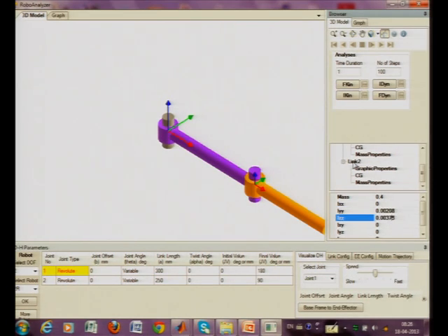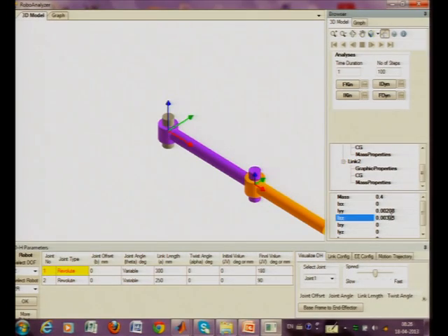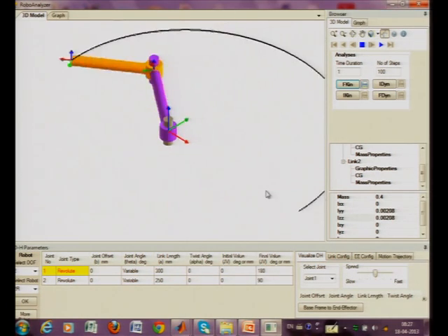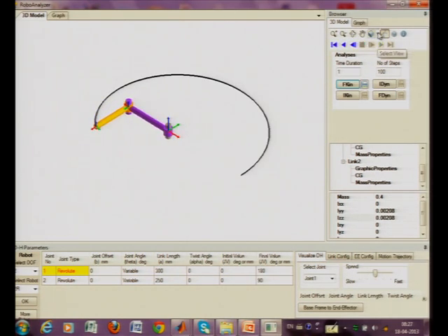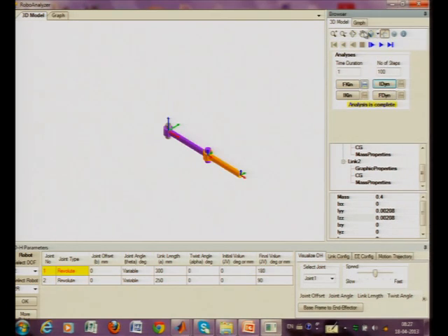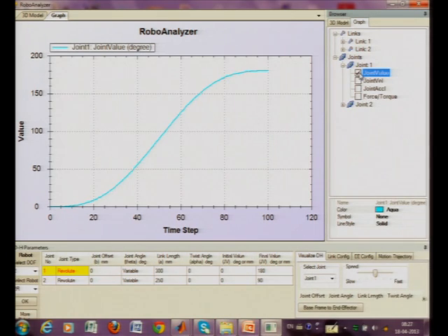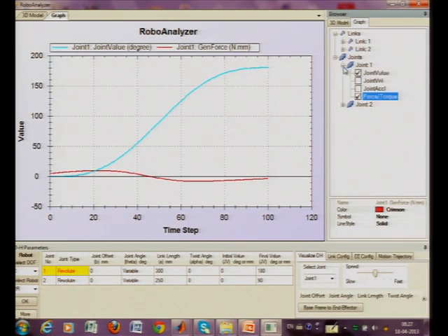I have selected here, okay, and I do not have to select from the window, it is only from the input panel. Okay. So, now I perform forward kinematics, that result can be seen, okay, and then I do inverse dynamics and I see the plot, and the joint value was varying like this, and this is the joint torque.